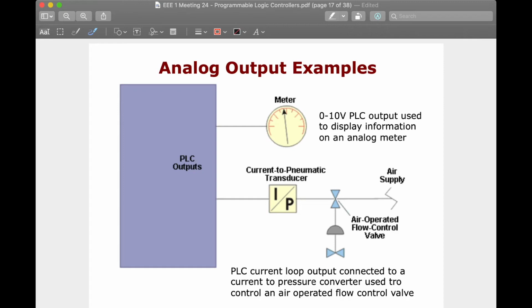At the same time, for the analog output, you have this transducer. The relay coils are usually here. The relay coil is attached to this transducer that translates the electrical signal into some mechanical signal that controls the valve, which then controls the airflow of our air supply.